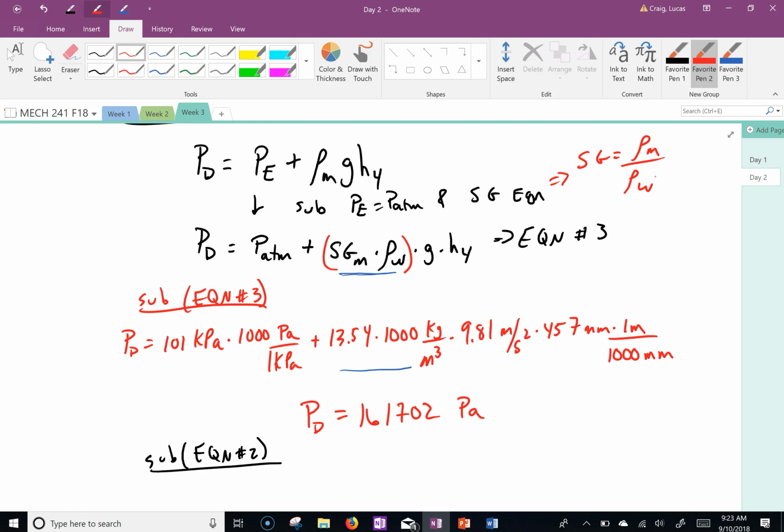That would be a messed up conversion. Yeah. But what do we typically use? Yeah, cubic feet for the volume. Yep. But what is it, either pound mass, like you guys said, or slugs? So always remember density of water as 1.94 slugs per feet cubed. Because when you include that in your units, you'll end up getting a pound force at the end. You don't have to do that weird conversion.